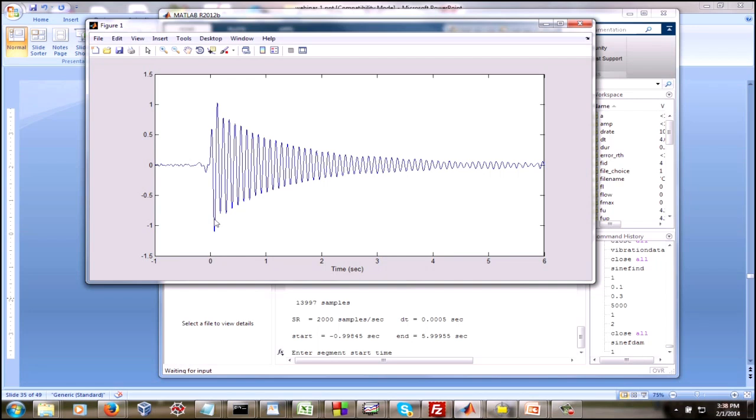Now, a static deflection shape is not the same thing as a dynamic mode shape. There could be some close similarities, but the two are actually different. So it actually takes Pegasus a couple of cycles to wiggle out of its static deflection shape and go into a pure dynamic bending mode shape. So that's what you see on the onset there.